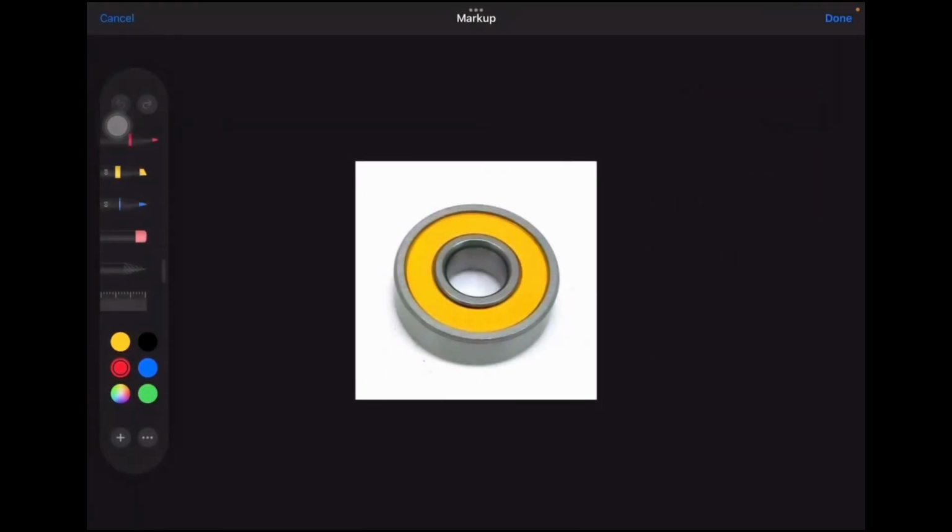One of the most important aspects that you need to have to roll from one point to another point will be the bearing. As you can see on the picture here, we have a bearing being made from steel, and a standard size for the bearing is an industrial standard size of 608. You cannot see it clearly over here, but basically if you have the bearing with you, you can see the number being printed on the cover of the bearing.